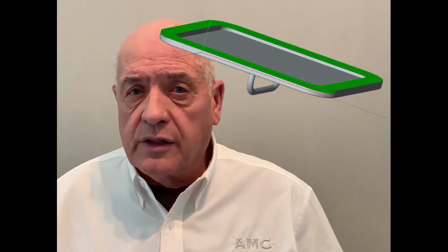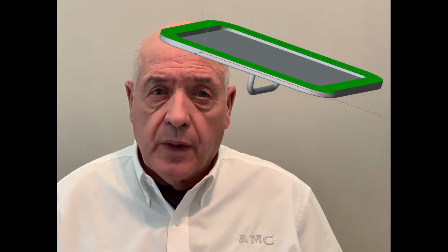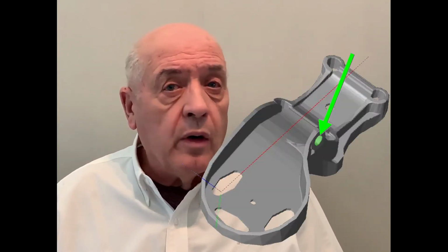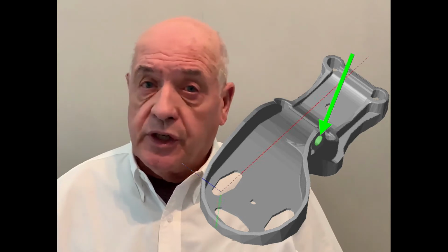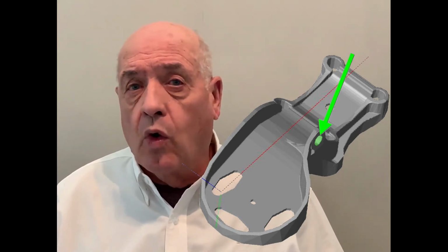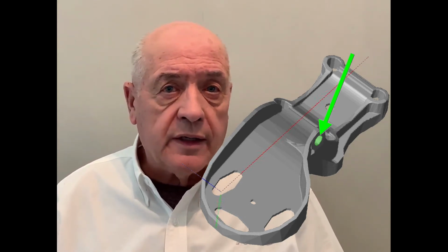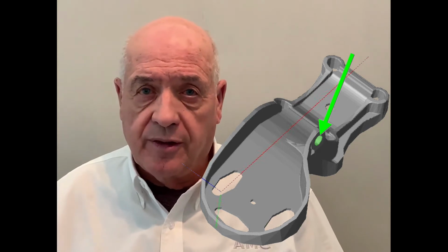In other words, enough machine stock thickness in the correct location to mill or turn a surface to net profile, or sufficient as-cast position accuracy to drill or bore a hole with correct net size and position.